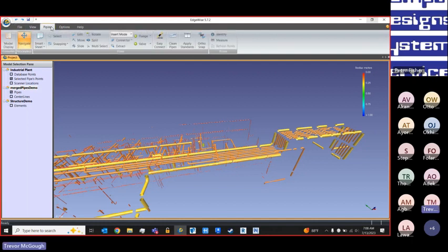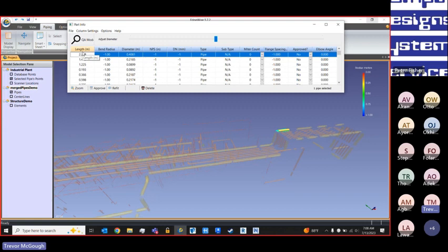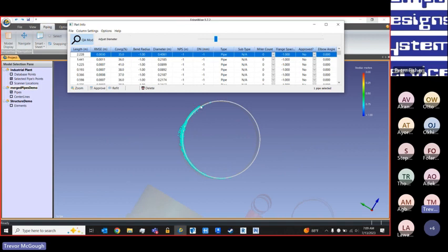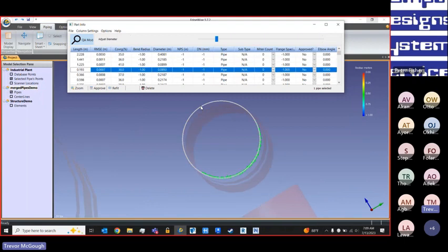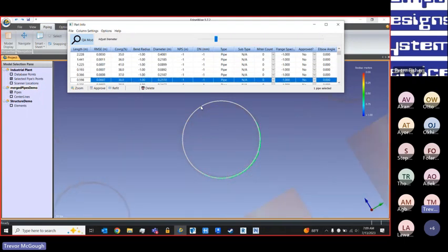So the first key tool I want to introduce inside of EdgeWise is going to be our QA/QC tools through the part info spreadsheet. This is an intelligent spreadsheet that links my numerics back to my visual model. And coming back to that concept of QA, in the QA mode, I have the bore of the extracted pipe in gray, and in this teal/green, I have all the points used to extract that pipe. So I can very quickly scroll through doing a visual inspection of my pipes, and that way I can ensure the highest level of accuracy in the geometry fitting the point cloud.